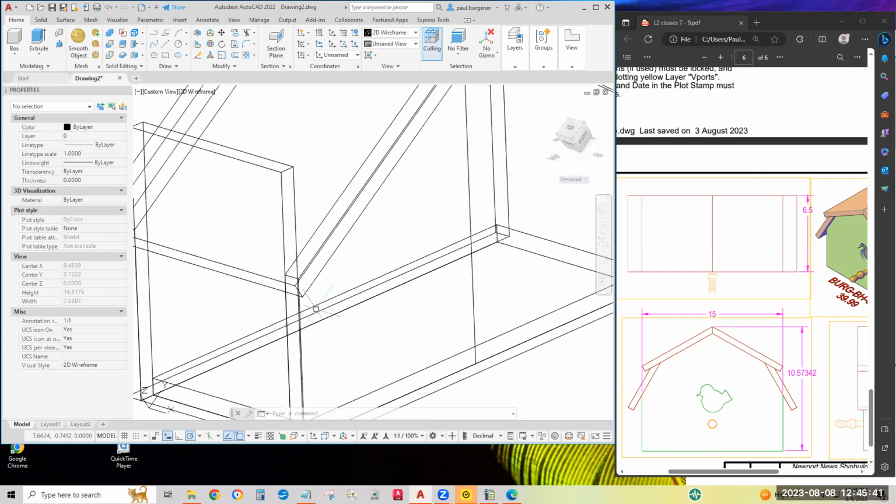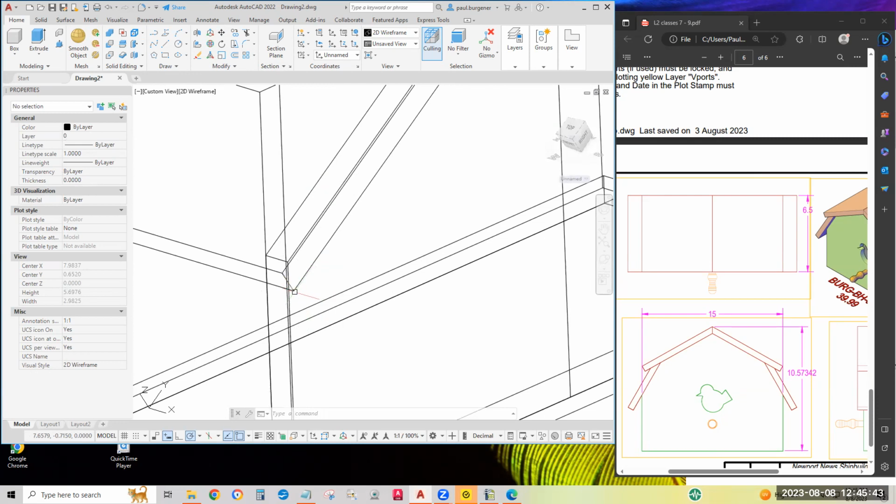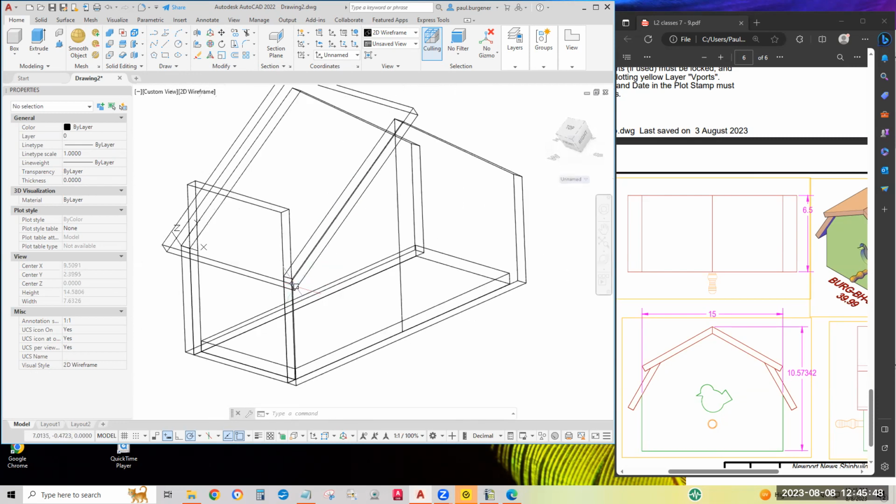Okay, we want to slice it using, for the slicing plane, 3 points on the bottom of this roof panel. And that'll slice this board so it's got a little glued surface, a little edge touching the bottom of the roof for another bead of glue, and a couple of tacks or screws for good measure.